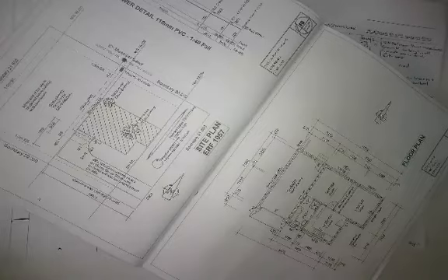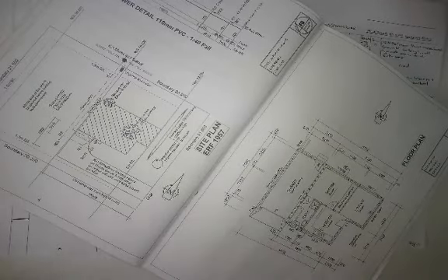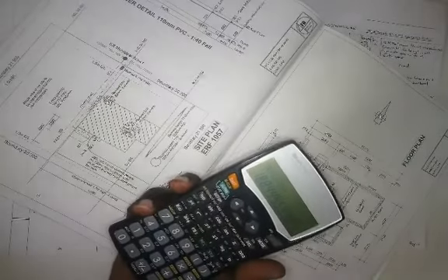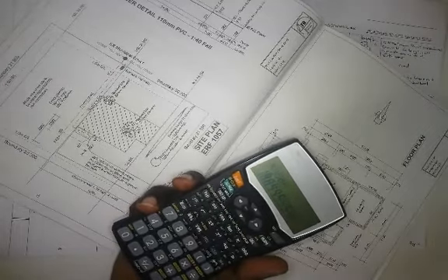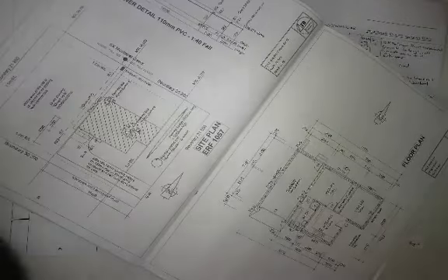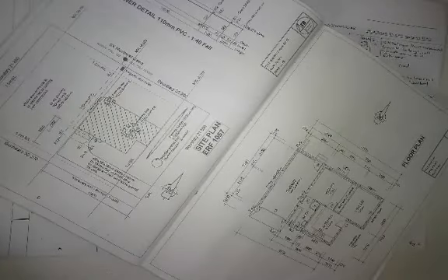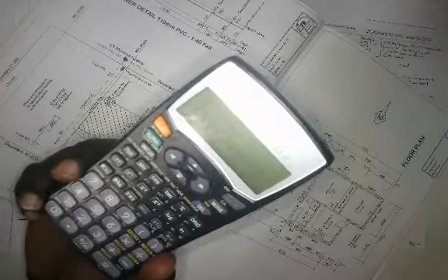So basically, just go to your drawing. Here's a 60 millimeter diameter. So they say it's pi times diameter. So that's 60, so that's like 188 millimeter girth. So it doesn't exceed 200 millimeters. So this one falls under the first description that says clear site and small trees not exceeding 200 millimeters. Okay, guys. But for instance, this tree now is 210 millimeters in diameter. So you get about 659 girth.